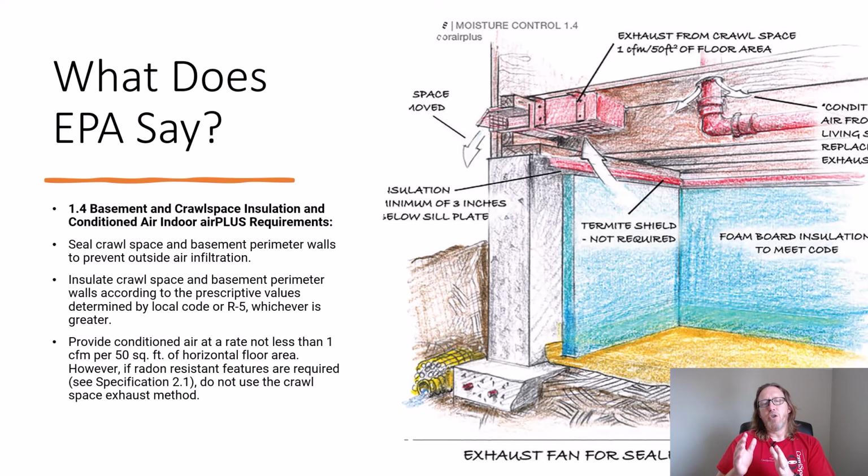If you have been tested for radon and found that your home has high levels of radon, they don't recommend this as a radon mitigation system. They recommend you install a radon mitigation system. But if we're talking about just basic soil gases, you want a rate of no less than 1 CFM of air for every 50 square feet. The Lamanco PCV1 fan, for example, does up to a 5,500 square foot crawl space based on that formula.